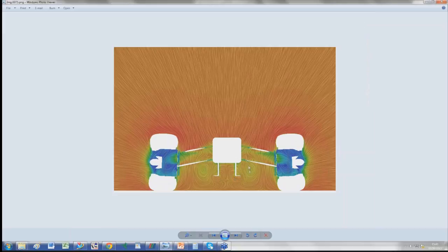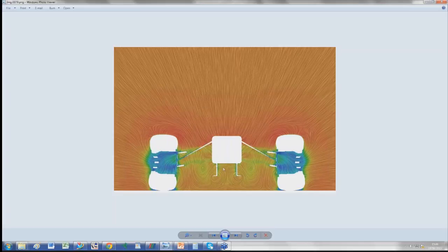And this is combined with the big one, effectively a system that works together. The reason for having these vanes is to control where the big Y250 vortex is going to go. So you want to make sure it goes in the right place further along the car. This is how we work. We are moving around these vortices by adding components on the car.